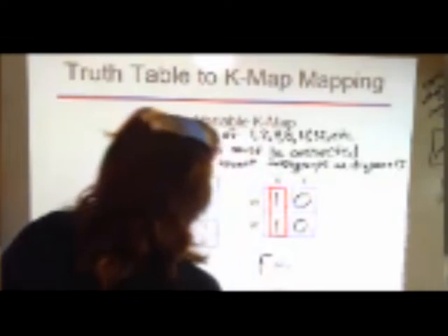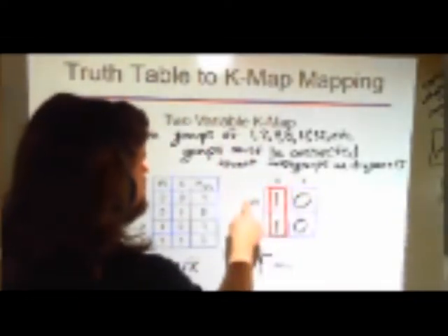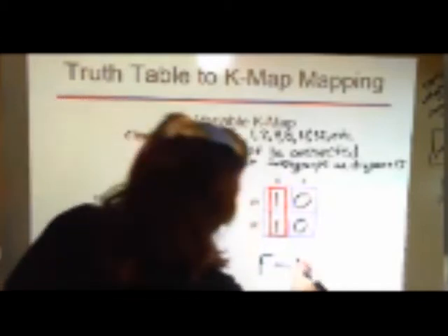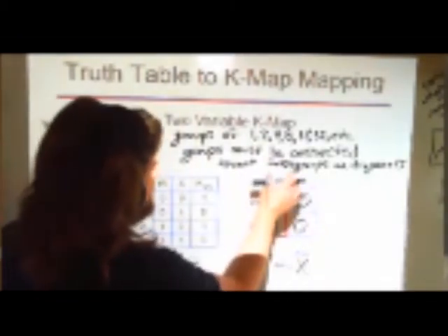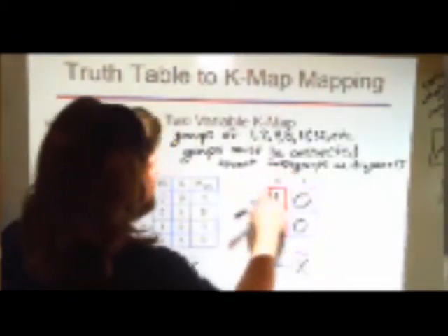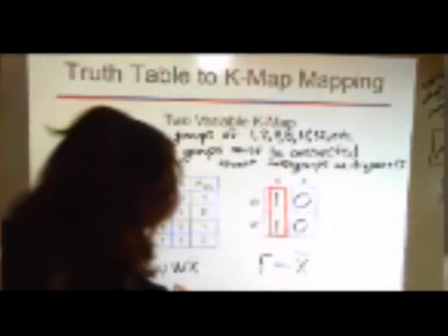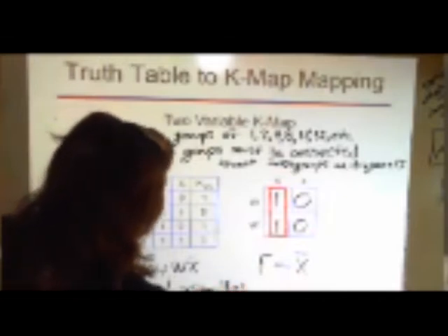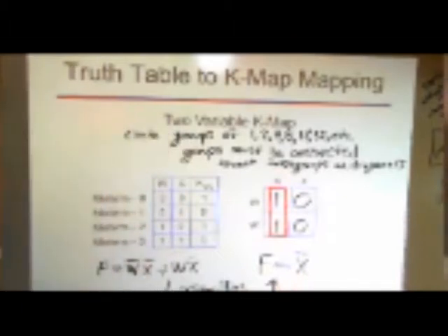What that does for us is we only include things in our logic expression that are in that circle and don't change. W in this one would have changed. We had a W naught and a W. That goes away. And this reduces down to just X naught, because X naught is the only letter in the header for this circle that didn't change. It just remained X naught the whole way through. And so this expression over here simplifies into that. We didn't have to do 9 Boolean algebra steps to do it. We just had to make one of these maps.